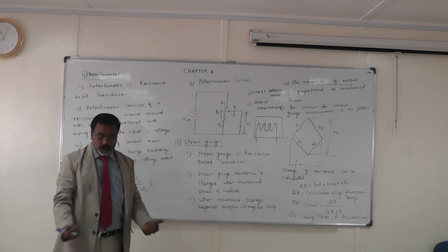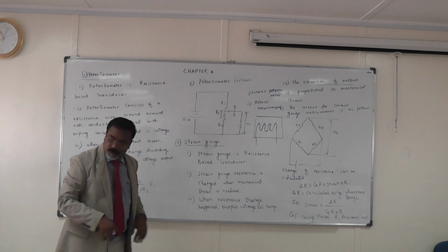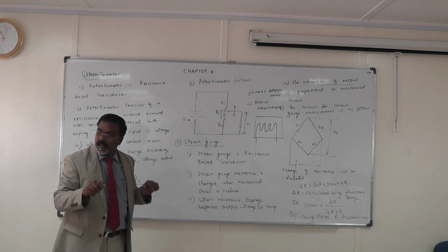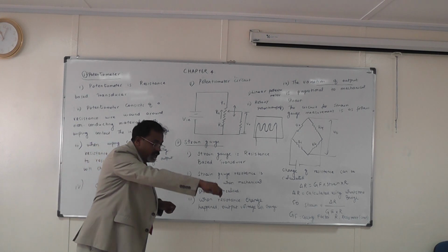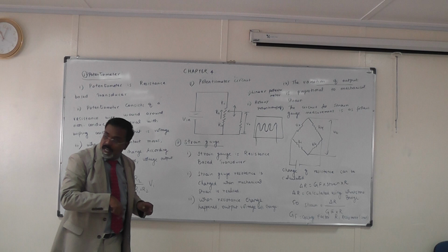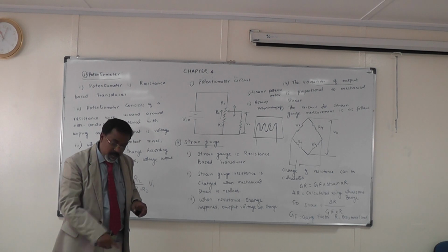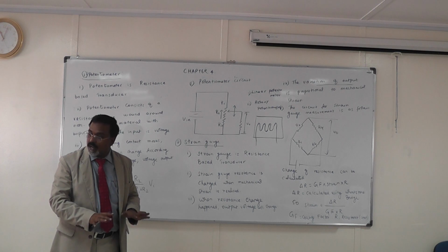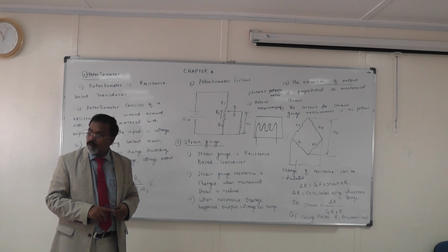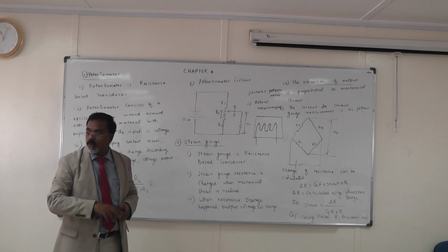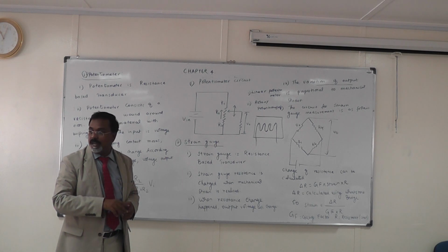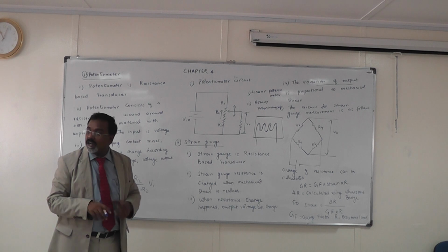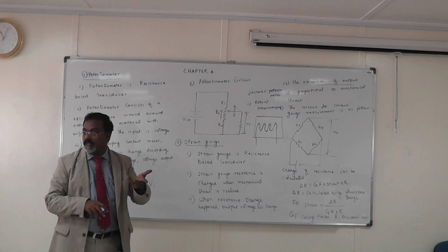For the other type, you can place one plate, and then in all four corners you place one pin, and then you tie one copper wire. When you apply some amount of mechanical strain on this copper wire, and you are giving some amount of electricity, the output of electricity will change because of this mechanical strain. So these types of strain gauges are called the unbonded type of strain gauge.